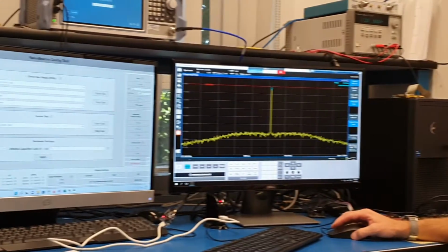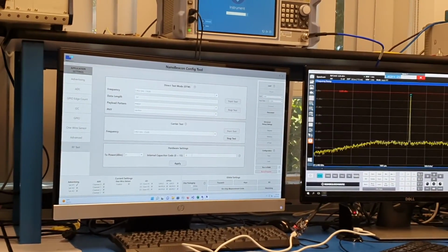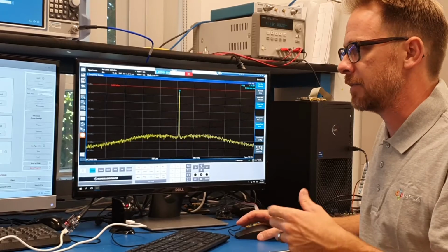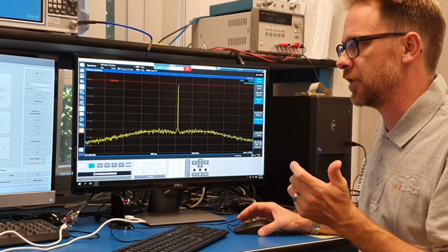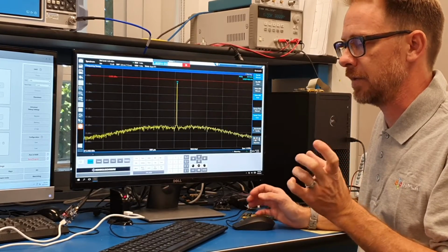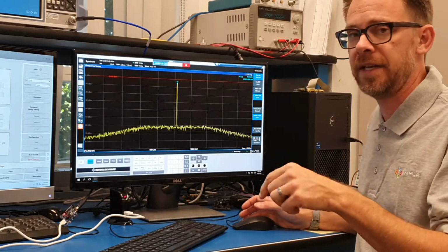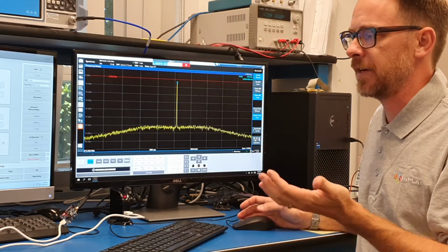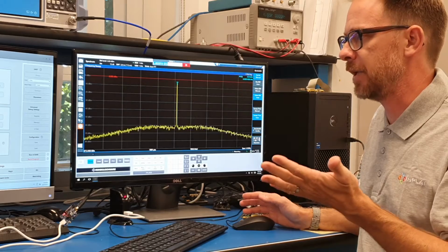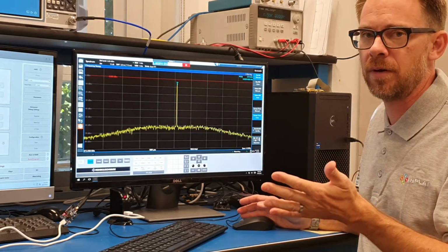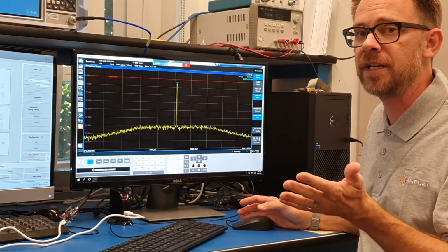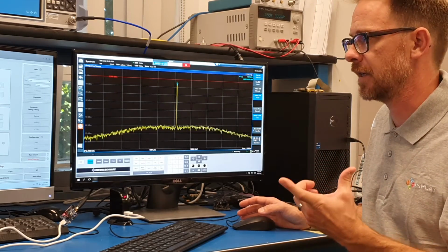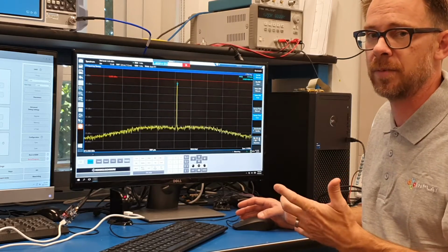And these internal capacitor codes actually represent how much capacitance is being used as the load capacitance on either side of the crystal inside of the chip. And they can be 0 through 15, integer. Each value basically steps up the load capacitance by 1 picofarad seen single-ended, or if you view that differentially, a half picofarad. So if the CL spec for this particular crystal is 8 picofarads, or let's say 7 picofarads, we know a capacitor code of roughly 14 or 13 would probably be appropriate, because it also has to include the board parasitic capacitance, the pin parasitic capacitance, and any other parasitics that usually total up about 1 picofarad.